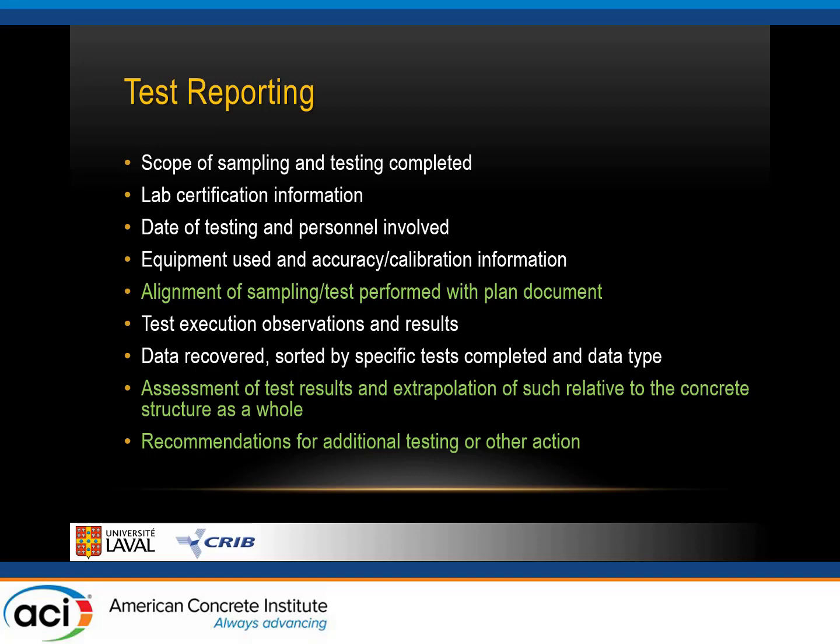I think we can use most of the different approaches here, since they are applicable to a variety of types of problems, including fire damage, and fire damage will often be evaluated that way. There was a part in the table that covered the tests for hardened concrete where fire damage is addressed, and petrographic examination will be one of the main tests that provide information on the extent of damage, the depth, and evaluation of the maximum temperature that was reached during the event.